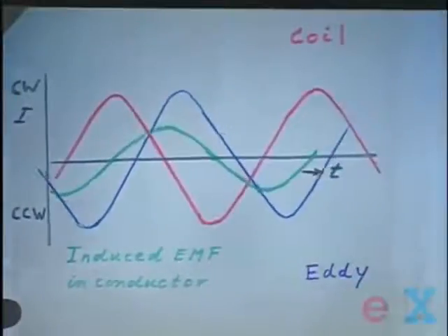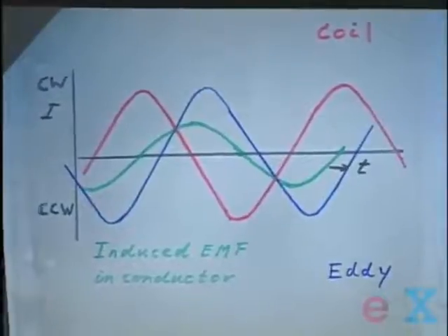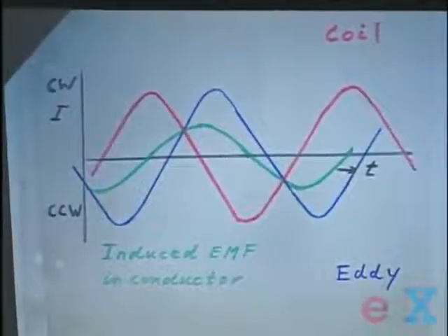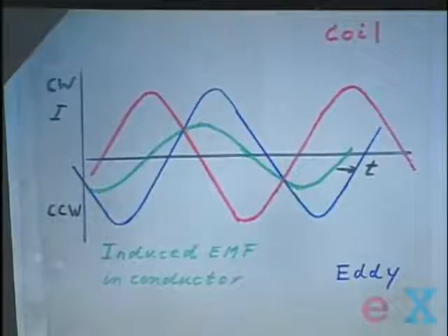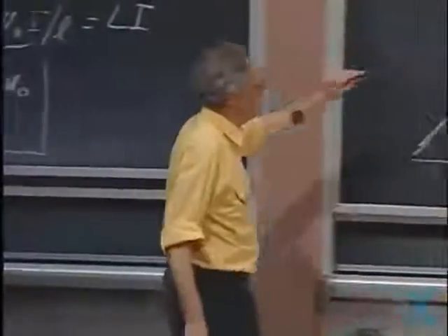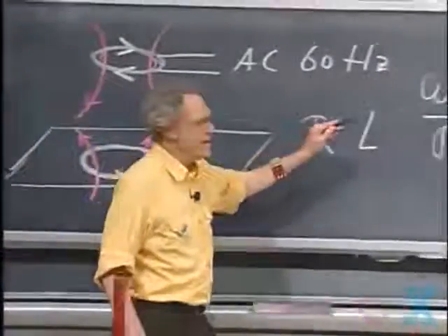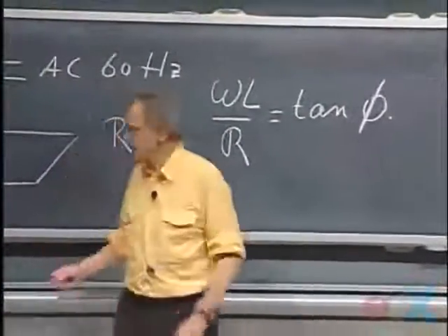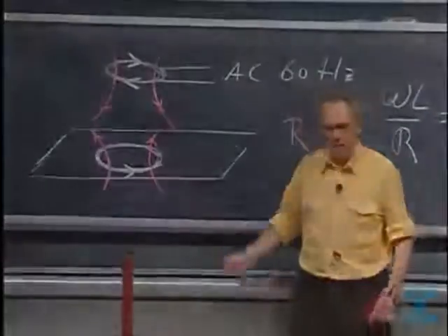Now in the case when we levitated the woman, I'm sure that the phase delay was not 90 degrees, but maybe it was only 30 or 40 degrees. But the net result is that you get on average a repelling force. And so the secret of the repelling force in the case of the levitation of this coil, and therefore of the levitation of the woman, lies in the fact that there is a finite self-inductance in here.